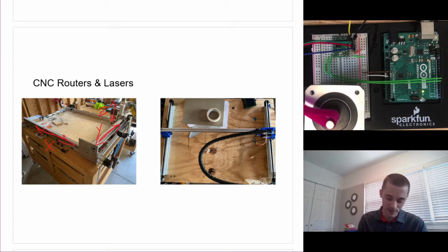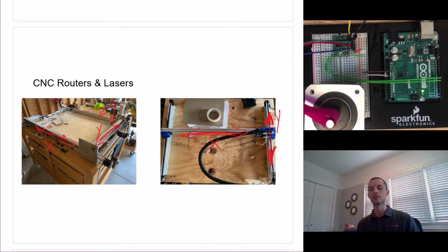On the right here, I have another setup where, instead of a 3D printer printhead or a router, I've got a laser attached to it. It's a small diode laser. I've got a CO2 laser one in my office at MSOE, but this is the Y-axis. Back and forth here is the X-axis. There's no Z-axis on this because it's a low-power laser diode.